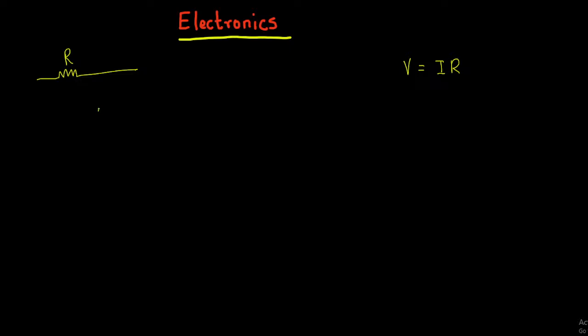And if we take a battery, here we will have the plus, which is the biggest line in the battery, and this is the minus, the smallest one. The current flows from the highest potential to the lowest potential, so it goes in this direction. This is the illustration, but what really happens is the electrons travel in the opposite direction. Current flow is the direction from plus to minus, electron flow is from minus to plus. R is the resistance right here.